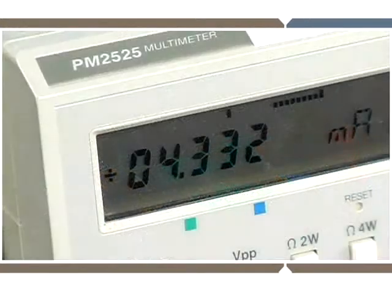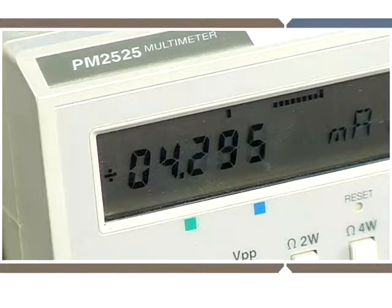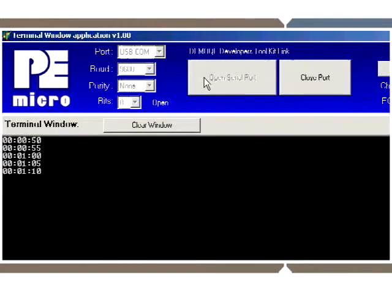As we cycle through the different modes, we will continue to monitor changes in average current consumption on our digital multimeter, as well as periodically check that our timekeeper application is still updating. The display will update every 5 seconds with the elapsed time since the last reset. In the LP run mode, the display is not updated, but the total count is continuously updated.